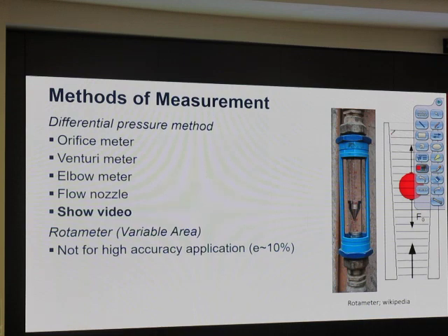10 psi. For the meter that I have in the lab, the accuracy measurement limit will be about 1 inch of water. Okay. If I get something about 1 inch of water, that is not quite measurable. 0.1 inch of water is for sure cannot be measured. Okay. 0.1 inch of water is very difficult to measure. 1 inch, maybe 0.5, we have more uncertainty.